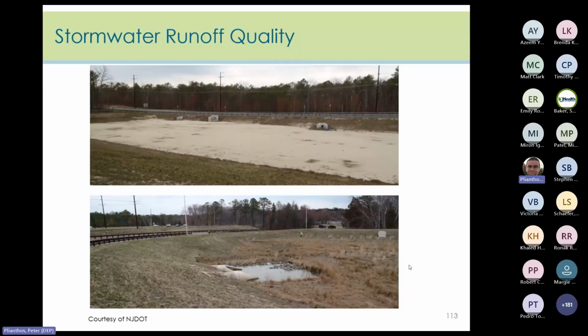The bottom one has established vegetation and ponding by the headwall. Ponding like this is going to affect the hydraulic performance of the basin, and it may lead to structural concerns with the headwall because of seepage and erosion. Also, this stagnant water becomes the perfect location for mosquitoes and algae, all things we want to avoid. And how do we avoid this? Post-construction testing to ensure it was built correctly, and proper maintenance.